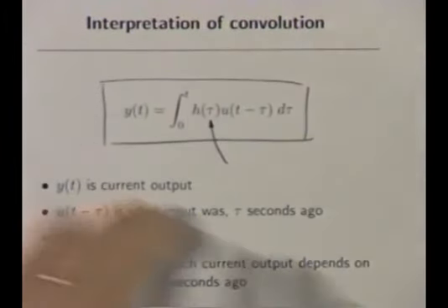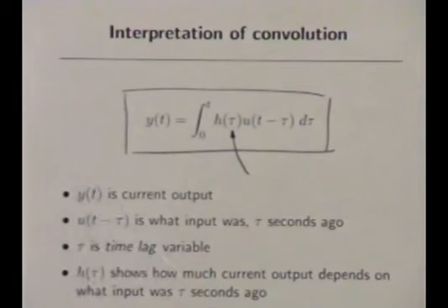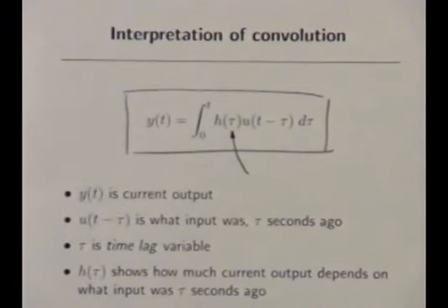It's basically just discussing what we saw last lecture in the context of circuits: if you have a circuit with inductors, capacitors, op-amps and linear elements, all initial conditions are 0, and you have a source like a voltage or current source that drives it, and an output as a current or voltage somewhere else in the circuit, then the relation between the input and output is that of a convolution.